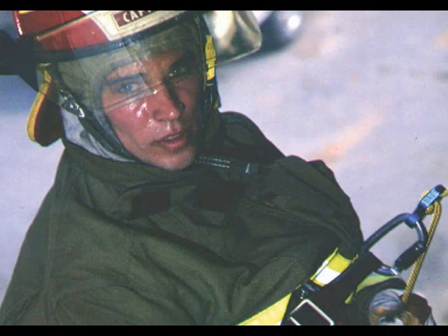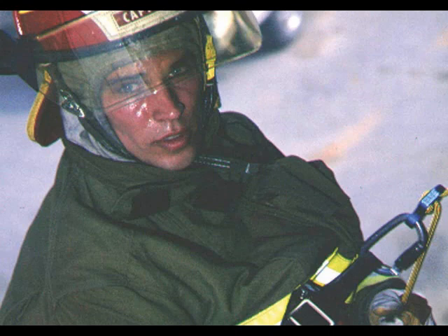Another specialized environment is fire rescue, and the thing that leaps into people's minds when you say fire is heat. Remember, though, the high temperature working limit of aramids is still only about 350 degrees. Nothing is fireproof. You have to balance the concern that you have about heat with other concerns regarding the effect of repeated bending, as well as the fact that aramids have so little force absorption capability, which is important for a firefighter who's leaping out the window of a burning building and for his anchors.